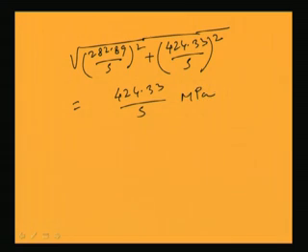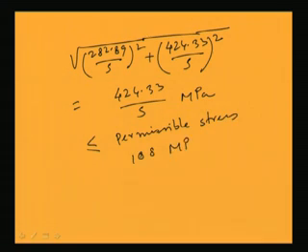Okay. So, resultant stress at the extreme point will become 424.33 by S MPa. Now, this should be less than or equal to the permissible stress. Permissible stress is basically 108 MPa.